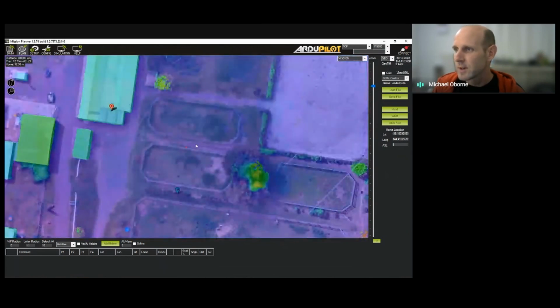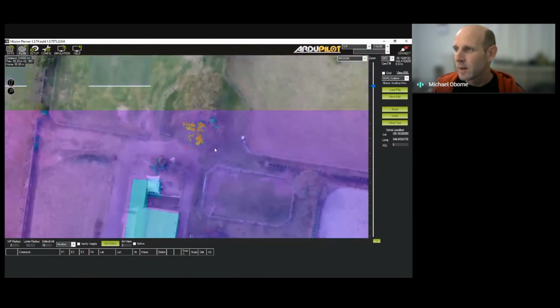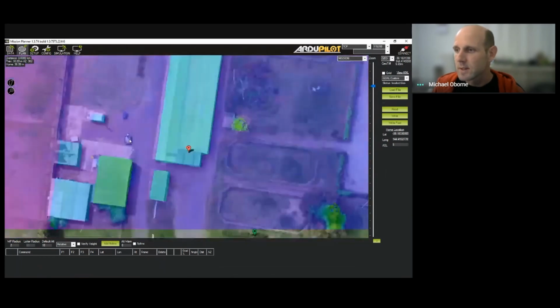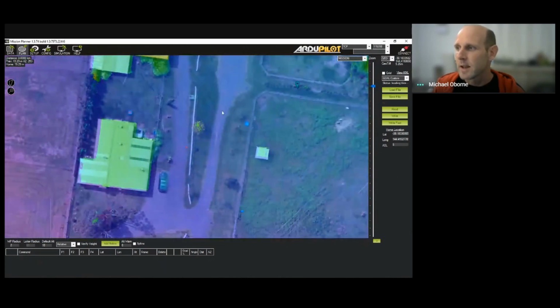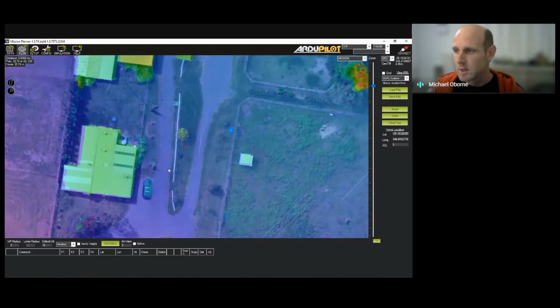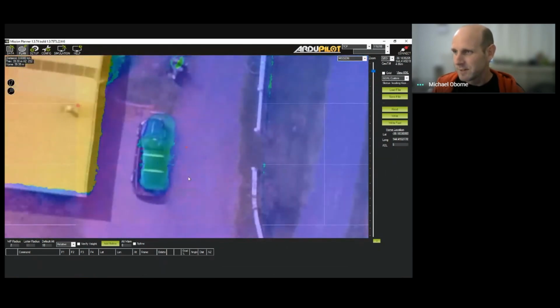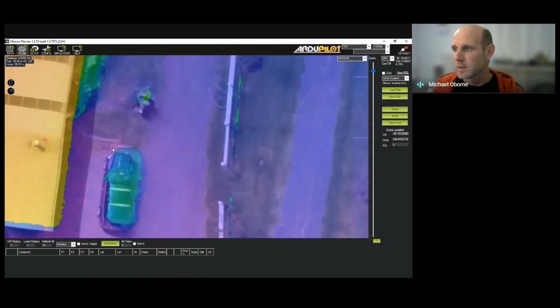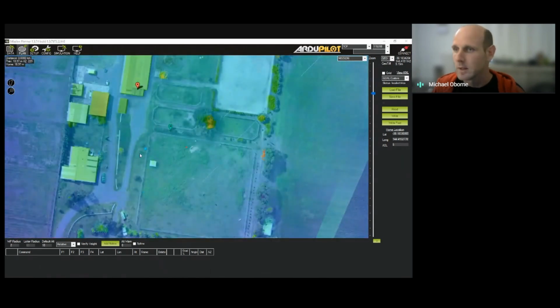There's obviously a very big tree just there, and other things like that. So it's a good way of checking the DEM is loaded, and it actually looks pretty accurate, which to me it does. There's a little bit of a shift in the DEM there versus the ortho photo. I did process this data in low quality though, so it's not too big, but it's not the best quality.